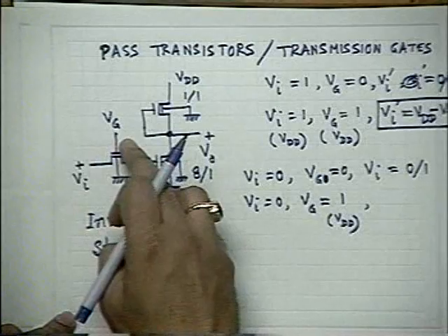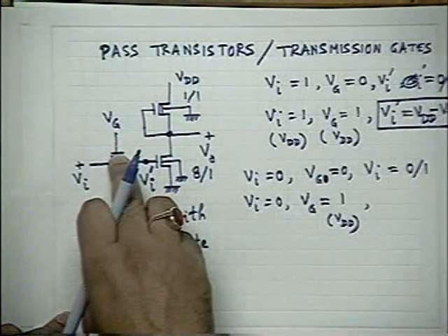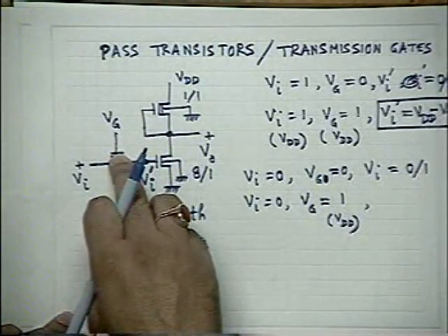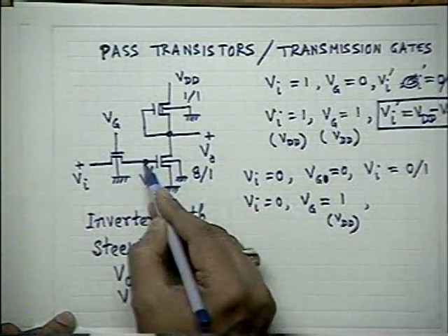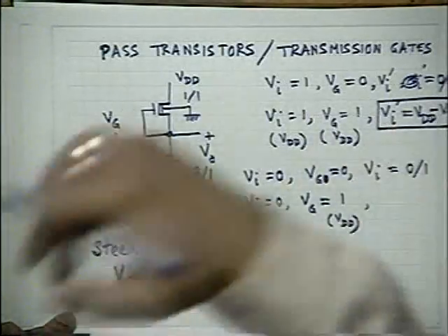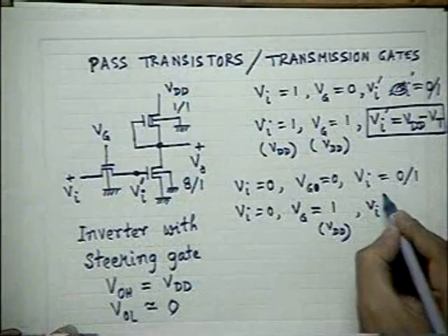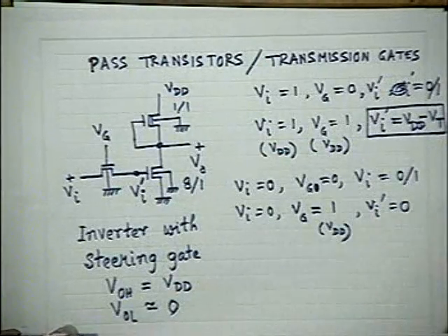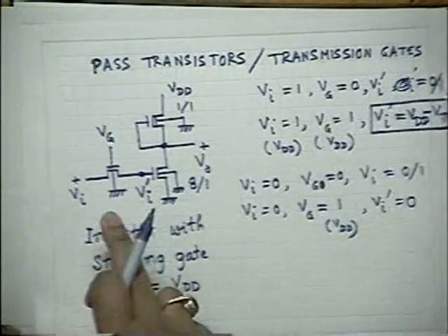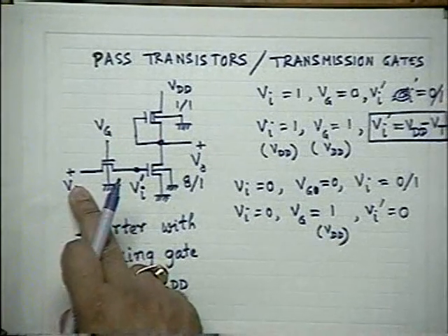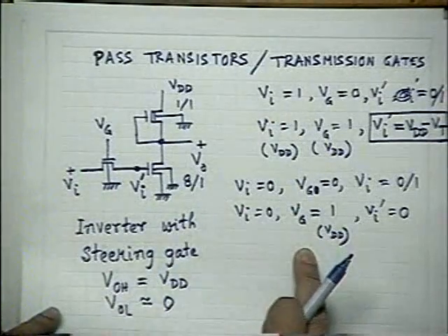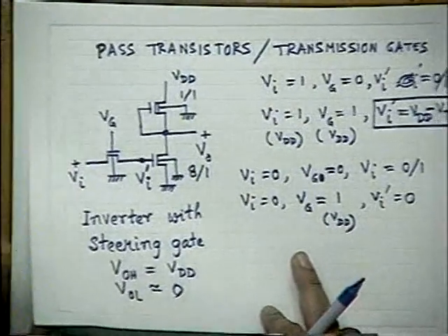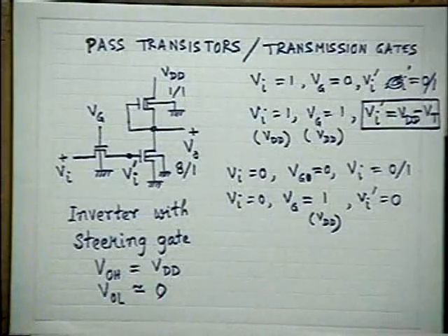And therefore, for this transistor, we have applied a voltage at the gate which is much above Vt. It is very properly on, deeply in the linear region, so whatever charge was there earlier in the last stage will discharge very properly. So it is assumed Vi dash is equal to 0. There is no problem here. When Vi is in a 0 state, there is no problem. Whenever Vi is high, then there is a problem. Okay? So this is a very important thing.